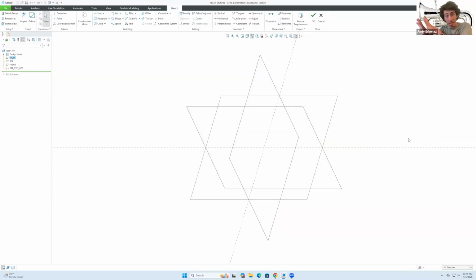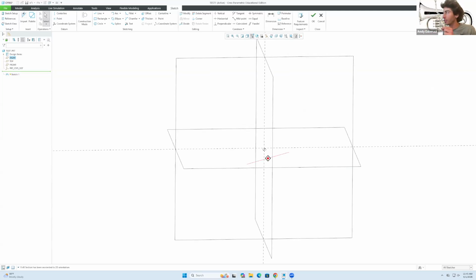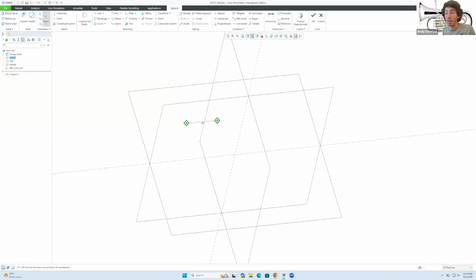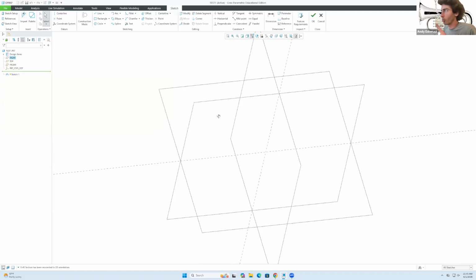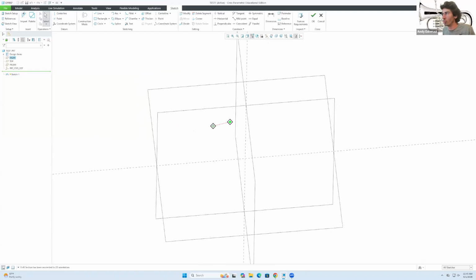Now the canvas becomes like this. I should mention that if you go to this little button in there, it's going to direct me towards the sketch view, which is, I selected that plane, so now we're parallel to that plane. If you look at your mouse, if you click on the scroll button, there we go, you can rotate things. Meanwhile, if you click on shift and then scroll, you can pan. Those are two very important commands. So this is how you rotate by clicking on the scroll button, shift and scroll button, you can move around.